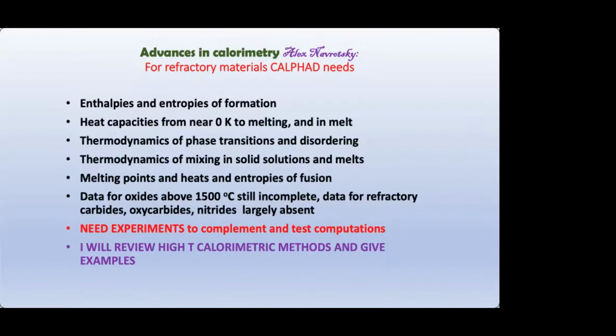So CALPHAD needs definitely enthalpies and entropies of formation of materials, heat capacities from near 0 Kelvin to melting and in the molten state whenever possible, thermodynamics of phase transitions. This means first order phase transitions, second order phase transitions, disordering transitions, determining what transitions are true stable transitions, what transitions are the evolution of metastable phases, thermodynamics of mixing in solid solutions and in melts, melting points and heats and entropies of fusion of high melting materials.